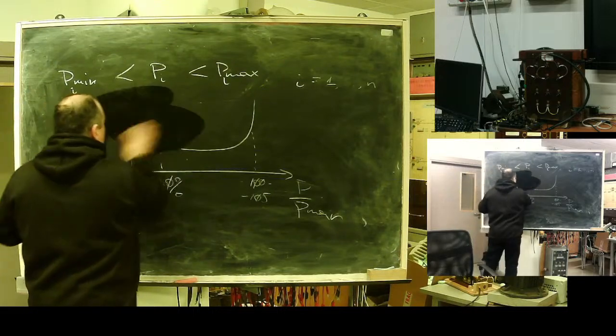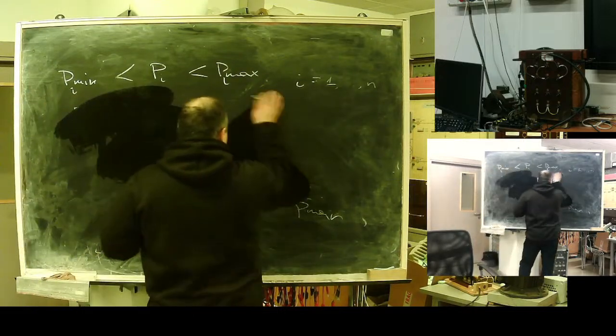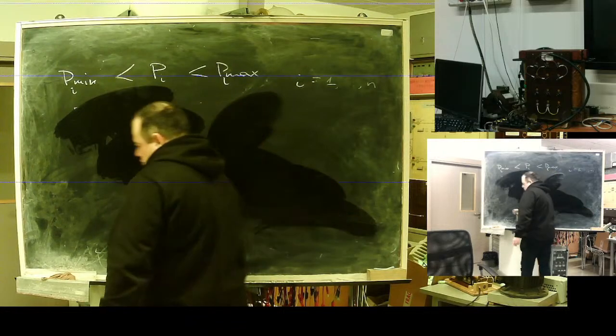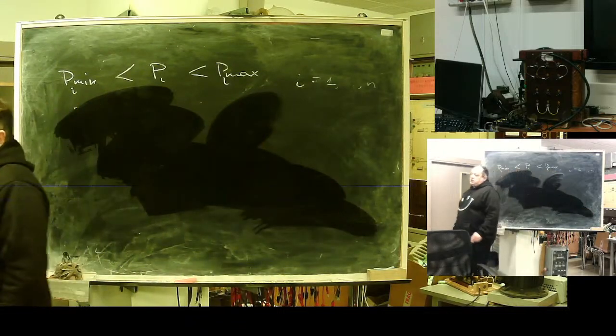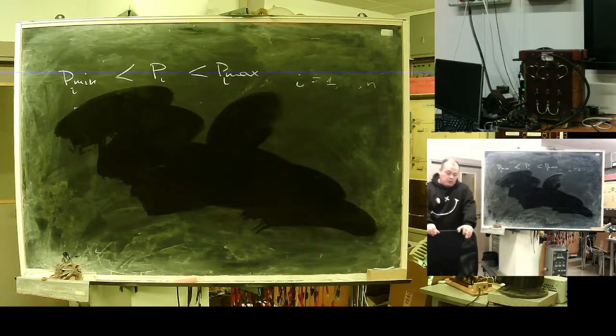For steam turbines, it is a bit of a different situation. For steam turbines, the limiter is the steam flow through the low pressure stage. It is determined by the thermal load of the low pressure stage.